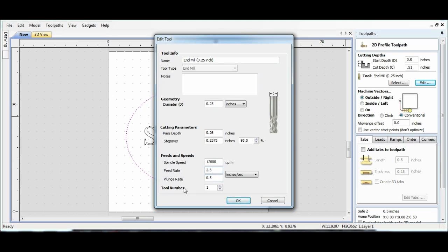Tool number does not mean anything. Once again, that's another feature that some more expensive machines actually have: a whole bank of tools that it'll change itself. It'll execute one tool path that needs a 1/4 inch bit, and if the next tool path needs a 1/2 inch roundover bit, you can name that 1/2 inch roundover bit tool 2, and it'll stop executing that code. It'll go over and grab the bit, install it, and then keep going down the line. That is a very expensive machine.